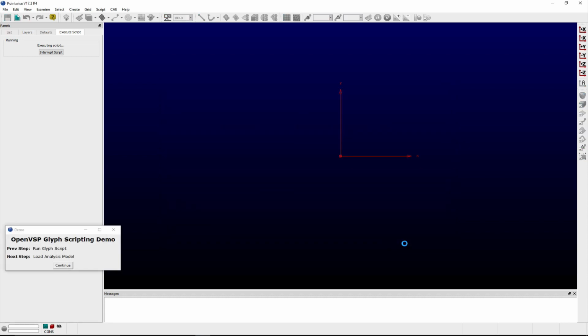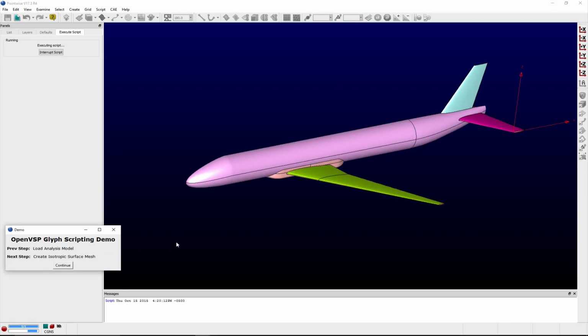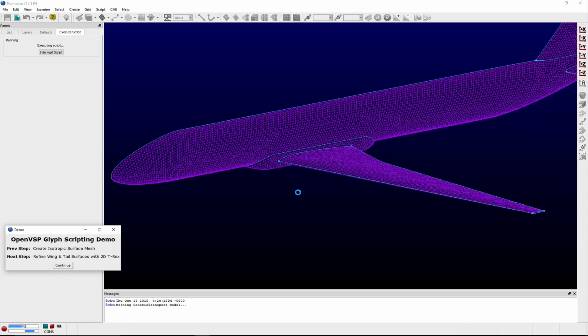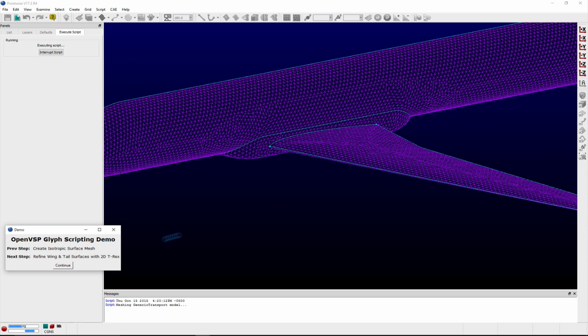The first thing the script does is create a database-constrained isotropic mesh on all of the surfaces using the initial user-specified surface average edge length. The connectors and domains created during this step are identified and assigned descriptive variable names based on the unique name given to each quilt. Identifying the connectors and domains that are created in this way enables them to be easily referenced later on as needed.